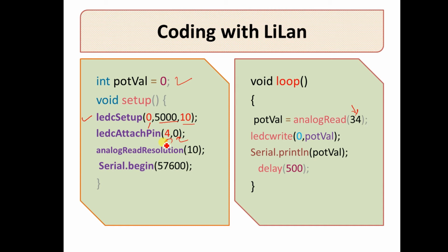Now, we also have to set the resolution. That is 10-bit, we are setting the read resolution, because the reading and the writing resolution should be the same. That's why we are using 10 here. The choice is yours, you can use it or not, it is not required.